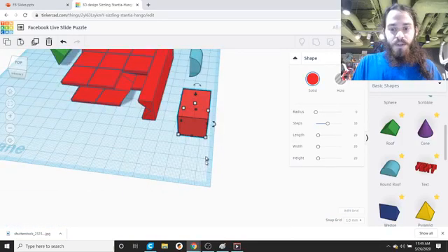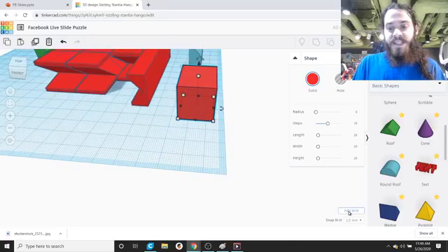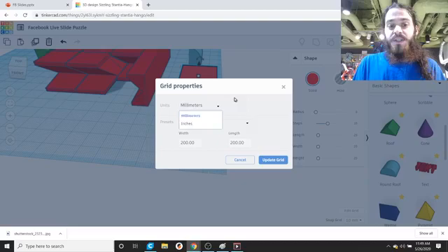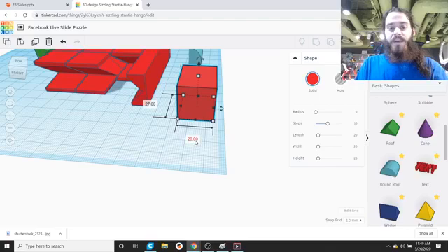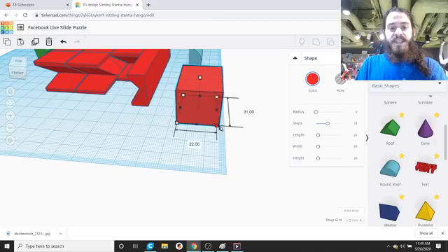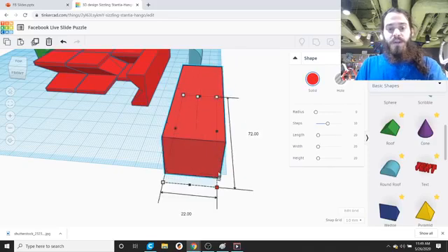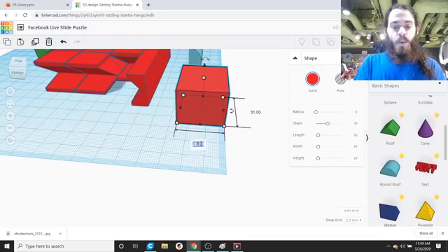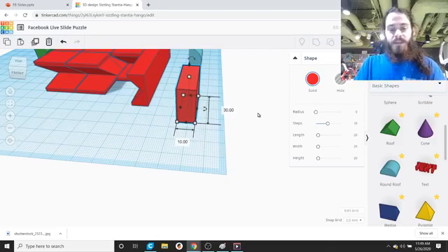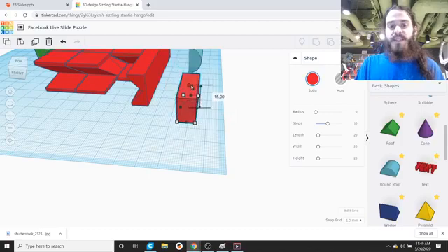So if I have this cube here, this edit grid shows your units, whether you're in millimeters versus inches, and you can say how big this base worksheet is. Whenever I touch these things, little numbers pop up. If I click here, I know that my cube is 20 by 27 by 20. If I start dragging it, you can see those numbers changing as I move it. And you can say, hey, I want this to be 10 by 30, and it'll happen. So you can also input dimensions like that if you don't want to move it like this.